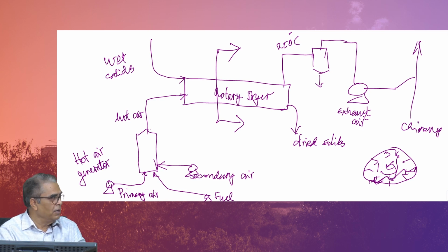and collect that information. For example, in my write up I have said that the first step any engineer does, because he walks in and is given a problem which is only slightly unclear, is go back and collect a lot of information about that situation from the sources. For example, we will go and collect the process flow diagram, P&ID, of that unit. It will be available, right? It is a running unit. So, we all said in class that in a running unit there is a lot of information available, historical data, everything. It may not be available on your table, but it is available somewhere in the company.